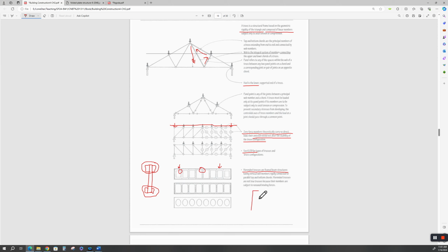Safest thing is to have round holes to lighten them up, because depending on how you load this box, these corners here are going to have a high stress concentration. High stress concentration. That's why ship hatches are not square. Because in the corners you have a high stress concentration, and you have a tendency for stress loads to go this way and crack or have bad loading. So you want to make your hatches have round corners. All right. So if it's round, the stresses in the corners are distributed out. They're not concentrated on the line of just the corner. There's no extra charge for that.